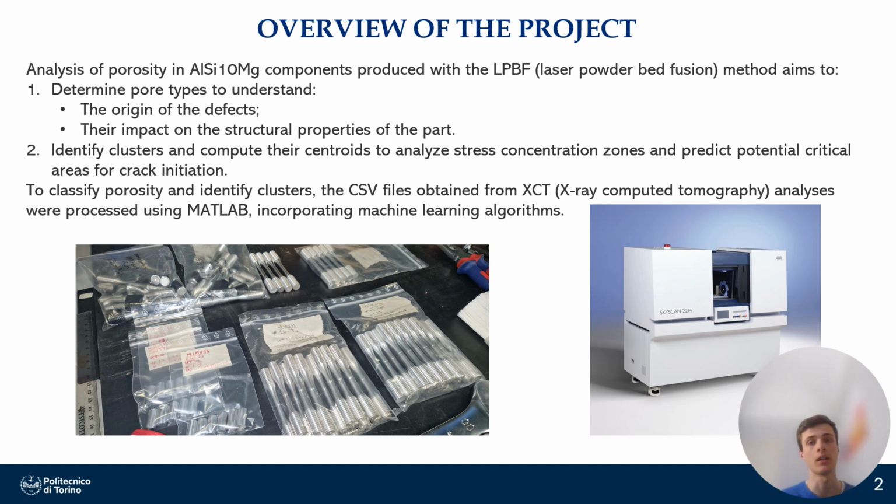The topic is the additive manufacturing of metallic material using the laser-based powder bed fusion method, an additive manufacturing technology that uses a high-precision laser to selectively melt thin layers of metal powder, creating a solid component based on a digital model. The process takes place in a chamber filled with inert gas to prevent oxidation of the powder. Each layer of powder is evenly spread over a platform and melted by the laser in the desired area. Subsequently, the platform lowers slightly and a new layer of powder is deposited, repeating the cycle until the part is